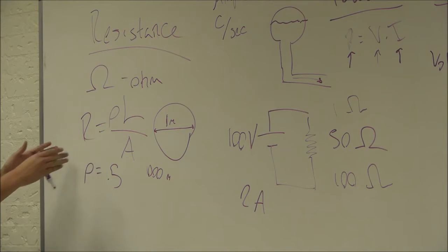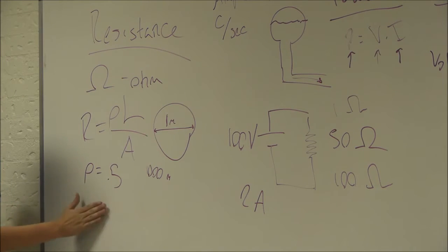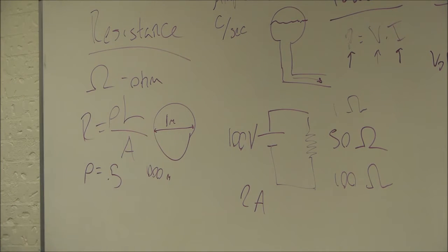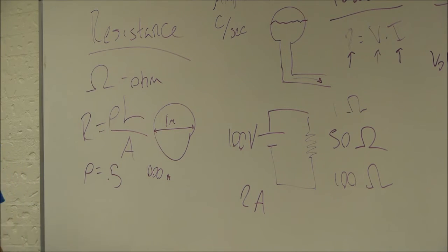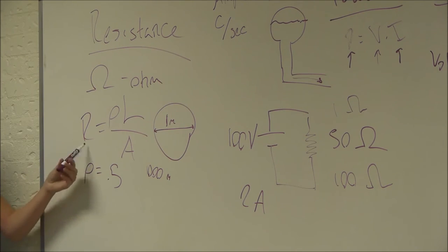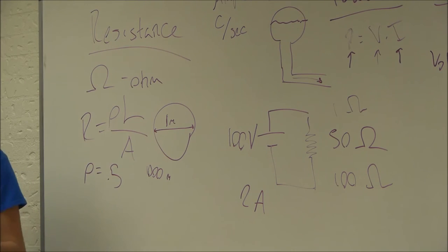So it's a pretty high resistance, right? You're going to lose a lot across that. So, I mean, realistic resistivity values are very low. So for copper, it's getting really low. Gold, even smaller. So basically for a long distance power transmission, you're going to want the biggest wire possible in order to minimize the resistance, because as you transmit power, you're losing it over that distance.